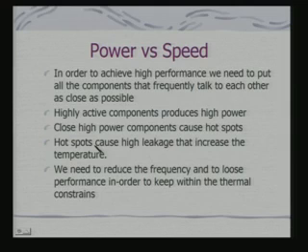Hot spots cause high leakage that again increases the temperature. So, we may need to reduce the frequency and lose performance in order to keep within the thermal constraints. This is the basic conceptual relationship between components which are determining your efficiency as well as power consumption.